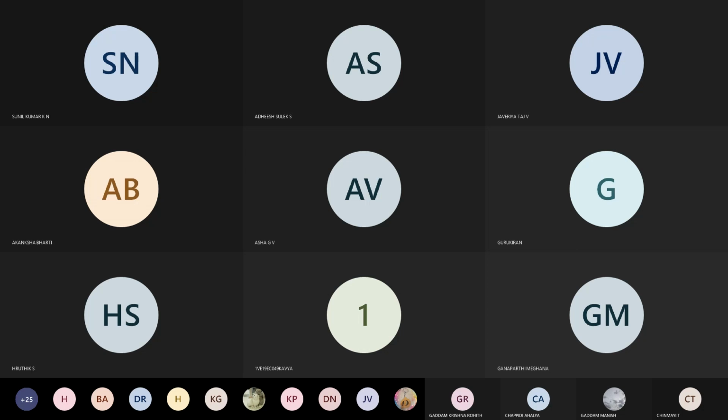So we need to see how you get this. This is the sum of the input voltages. Suppose we need to find the voltage V1 with respect to VA alone. What is the voltage across V1 with respect to VA alone? VB and VC will be reduced to 0. If VB and VC are reduced to 0, that means you connect them to ground.